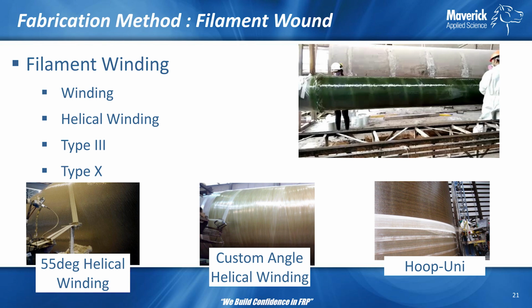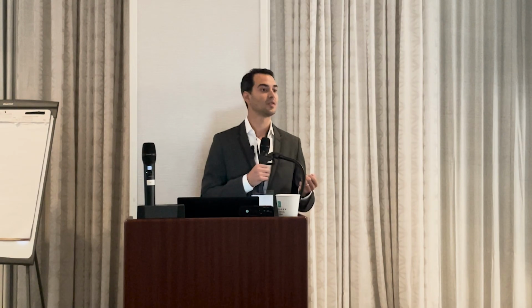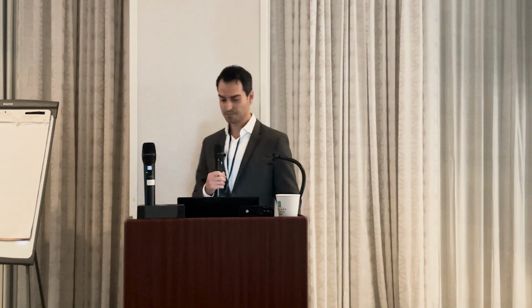So if you want to do a joint by using FRP, that will reduce the bond strength on that part. So that's why we recommend to always bolt these to whatever equipment you're trying to attach it to.